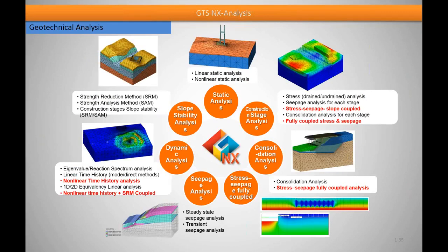Now talking about the GTS NX capabilities, you can see that in the static analysis it has both linear static as well as non-linear static analysis. Also in the construction stage analysis you can see two highlighted things, that is the stress seepage slope coupled analysis. Basically with Midas GTS NX, you can now consider the simultaneous effect of the same. Let's suppose if the seepage is taking place, how it is affecting the stress simultaneously could be studied. So a very real ground simulation is possible, and so is true with the stress seepage fully coupled analysis.